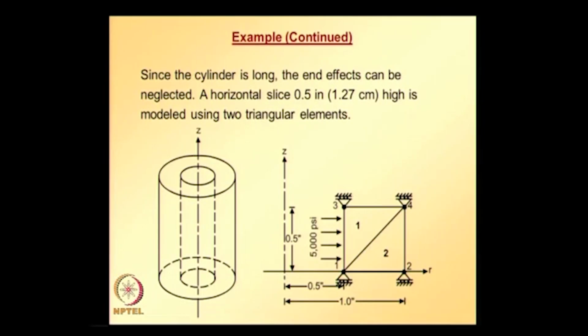Since internal pressure is applied from inside, the cylinder is going to expand in the radial direction, and since the cylinder is long, the displacement in the z direction is going to be neglected.